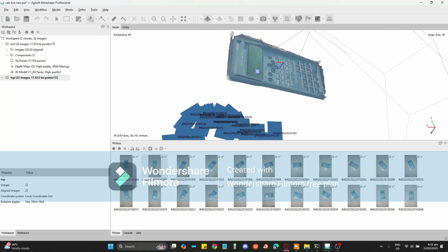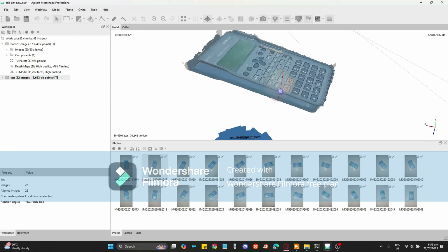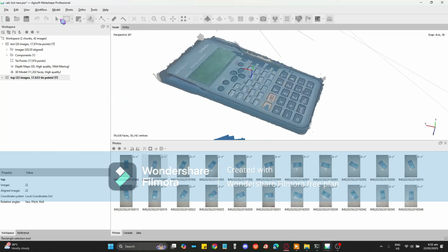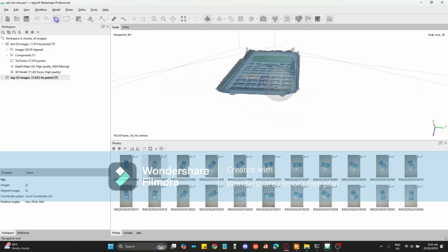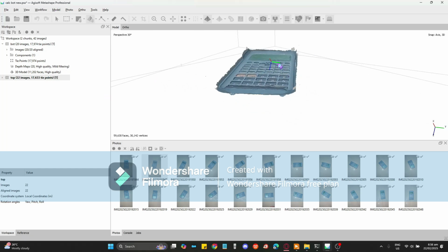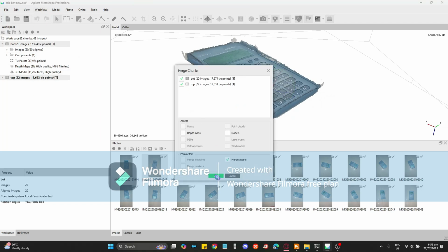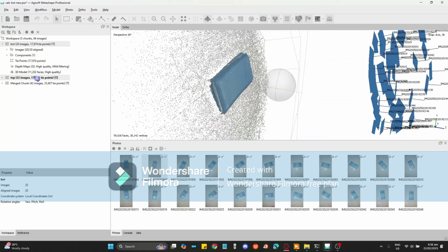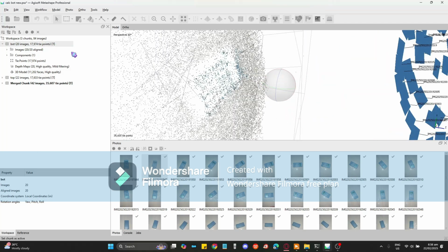So what we did in this process, me and my partner, we manually aligned the chunks using the transform function that can be found under the model tab. If you click transform, it has the option to make the chosen chunk object move. You can rotate it, you can also scale it. The following video will show roughly what we did in making the 3D object by manually aligning it, and then once it was sufficiently aligned, we merged it.